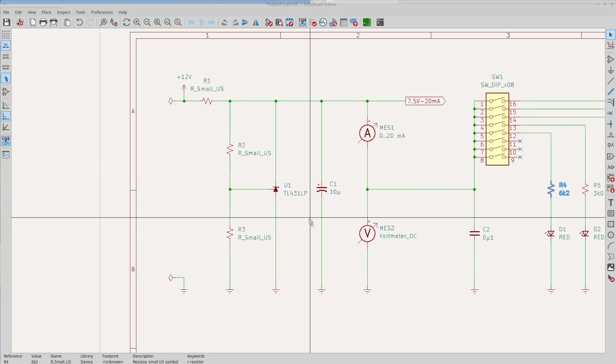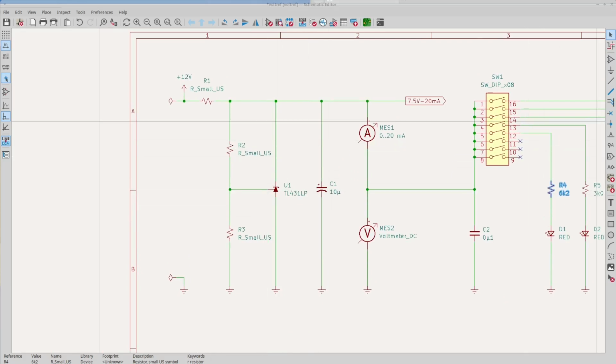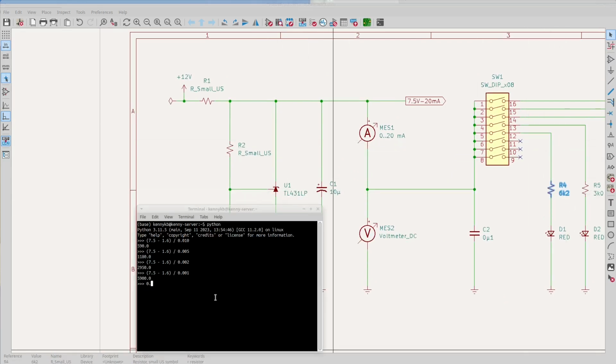The op-amp inside the TL431, like any real part, isn't an ideal op-amp. The datasheet says that the ref input can draw up to about 4 microamps. For the precision I want that to be less than about 0.5% of the current in the divider, so that I can ignore it.